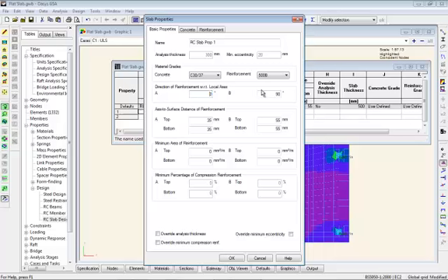Direction of the reinforcement, this is related to the element's x-axis. Defaults to parallel and perpendicular. Obviously you can set this to different angles to suit your particular structural requirements. Axis to surface, GSA is working out areas of bars rather than actual bars.